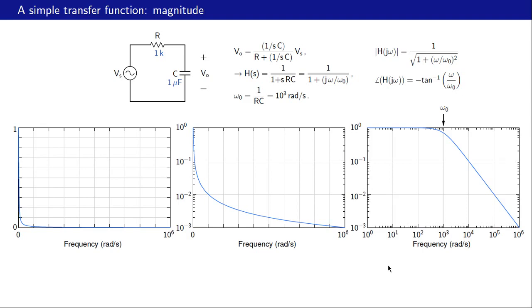What can be done is to replace the linear x-axis with a logarithmic x-axis as shown in this figure. This is omega equal to 10 raised to 0, 10 raised to 1, 10 raised to 2 and so on. And now we can very clearly, easily distinguish between different frequencies. And now it is easy to read the mod of h value for a given frequency. For example, 10 raised to 2, it is 1, 10 raised to 3, it is something like maybe 7 times 10 raised to minus 1, etc.